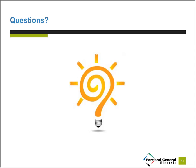Thank you, Gregory. And next question is, what rules of thumb can I use when looking at my energy data to help me determine if I need to make some changes? Primarily, it's comparing your historical data to today's usage. If you see a change that's greater than about 10%, then you really need to start asking some questions.